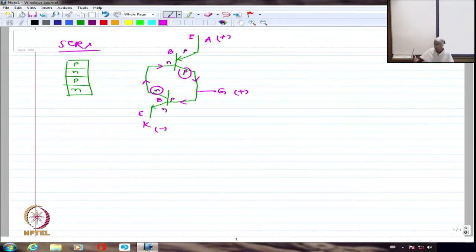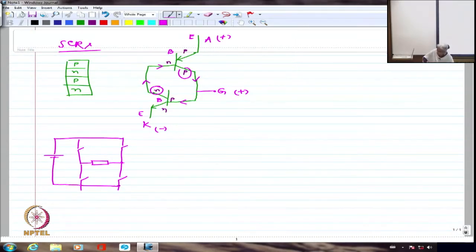If I am, for example, talking about an inverter, I had shown this inverter earlier also when I was talking about RL load and feedback diode. So this is an inverter circuit with a DC voltage as the input and AC voltage as the output. So this is going to be my inverter circuit. So if I say that 1 and 1 dash correspond to the positive half cycle when the current is flowing in this direction, okay, if I have 1 and 1 dash turned on, the current is going to flow in a particular direction. If I am going to have 2 and 2 dash turned on, I am going to have the current in the opposite direction, whereas this is going to be for 1 and 1 dash turned on, right?